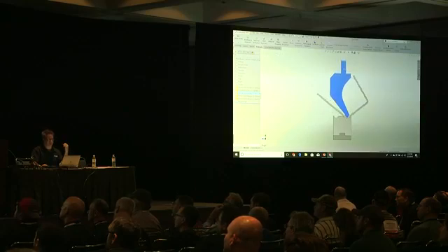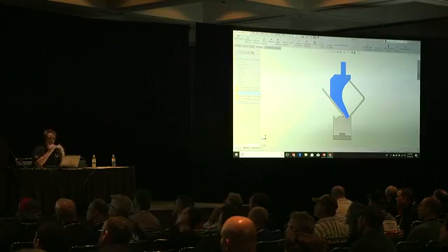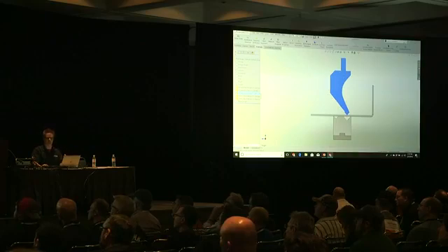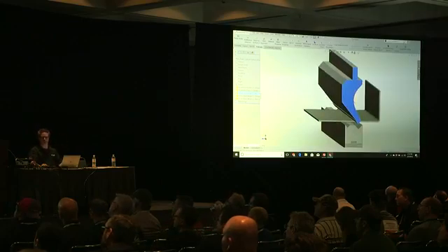Right about there is where it hits and starts to make noise, and then it really does weird things to the part. This is a special thing that he did with multiple parts to do the animation to make it look cool. All you need is the top and the bottom as an assembly. You drop your part in there, you make it to the bottom of the V die, and you bring this down and see if it's going to hit the back end of it.